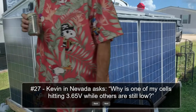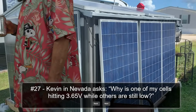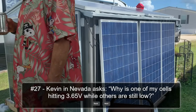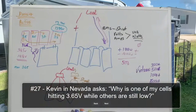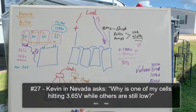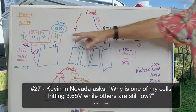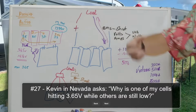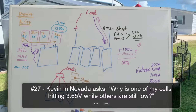And this would be directly related to your cells should all have the same amount of voltage, and they should all be the same voltage, or as close to the same voltage. And so balancing is required once you get to be 10 millivolts or 20 millivolts out of balance.